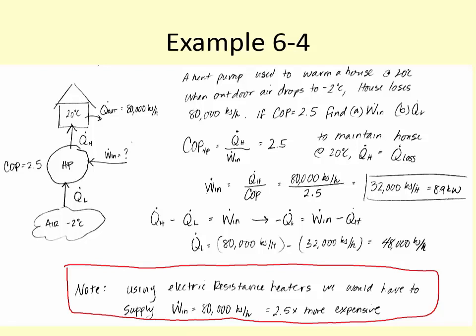On your heat pumps, you may have an emergency heat setting, which in a lot of cases is just resistance heaters inside the ductwork, or sometimes there's a backup furnace. If it's the resistance heaters, it's a lot more expensive to run your heat pump in emergency mode than to just run it as a normal heat pump. Emergency mode is for days where it's so cold outside that your heat pump can't keep up, and it needs to run a defrost cycle because the compressor's outside and it can get frozen. When it runs the defrost cycle, it switches from being a heat pump to a refrigerator just for a moment to defrost everything, and then switches back.